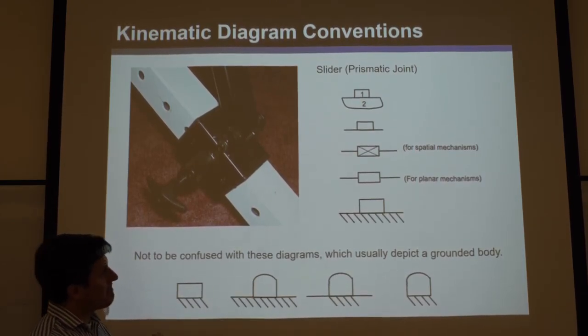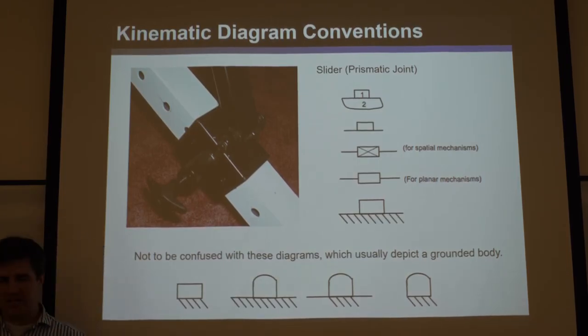Okay, so yeah. Anyway, it's a little confusing, and honestly, not all the conventions hold true. So sometimes you just have to ask your teacher what it is, or the engineer, or use your common sense and say, would anyone design a mechanism that is just grounded there, or should it be sliding? And then do your best guess. But this is the most confusing thing in skeleton diagrams.